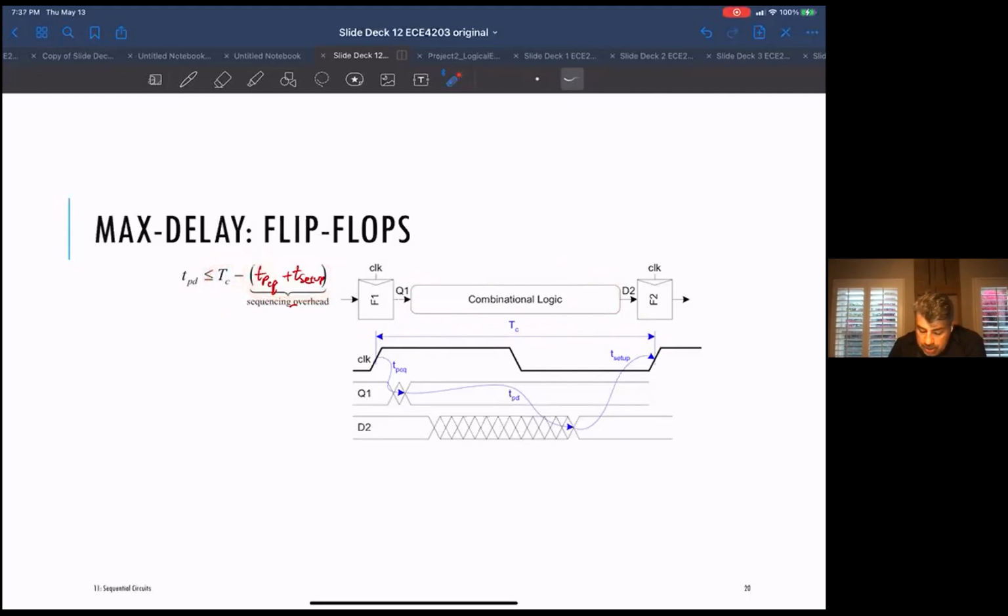So if somehow you made a mistake and you were looking at a clock period of 500 picoseconds and your chip's hosed, you can change that to 550 picoseconds and your chip works. It's not the greatest thing from a marketing and sales perspective because your customers are expecting a certain performance, but at least you have a working device.